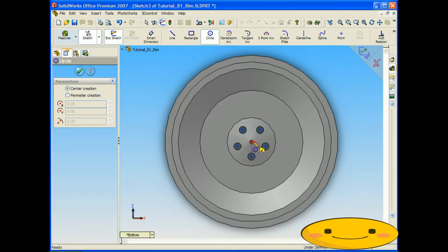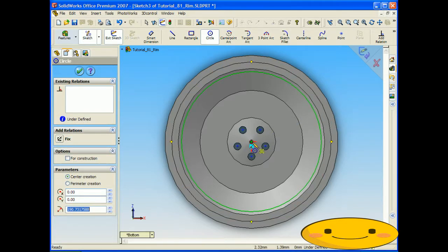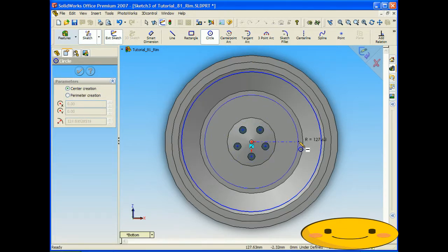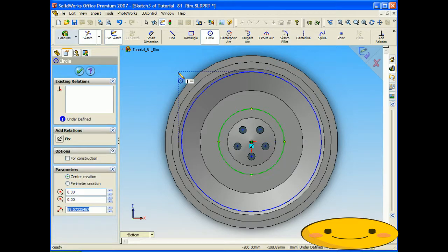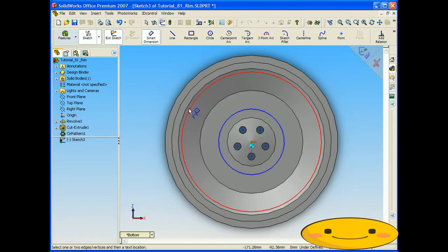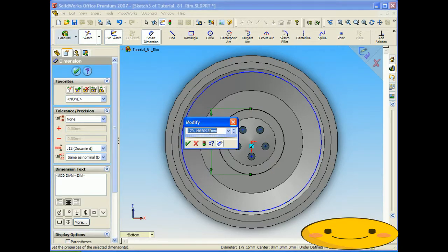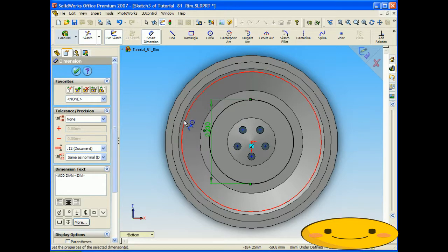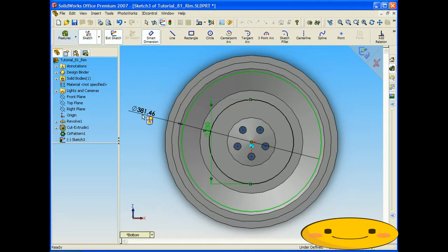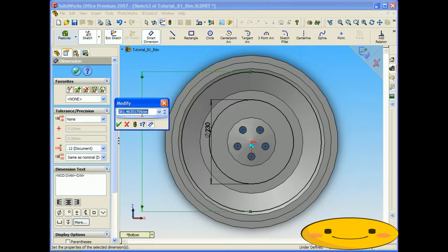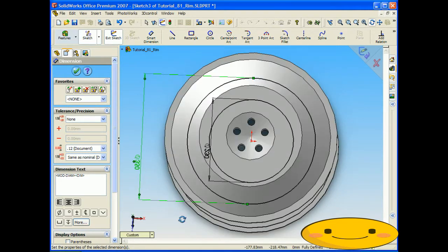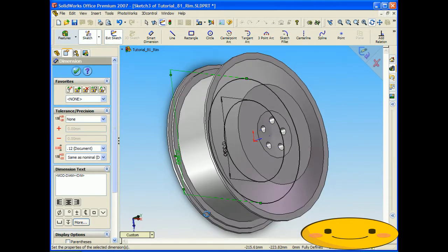Now our first sketch that usually we would put way out here, we're going to make it touch this line and then just come in a tiny bit. And let's click this point here, pull it out. Now click Smart Dimension. So what we can do here is, like we did before, we usually had like a 220 or 230 radius, so we can do that. Now with this radius here, we can either make it smaller, we can say make it 350, and we can look around and say that's like the cutout that we want in this rim, in this design, we can do that.